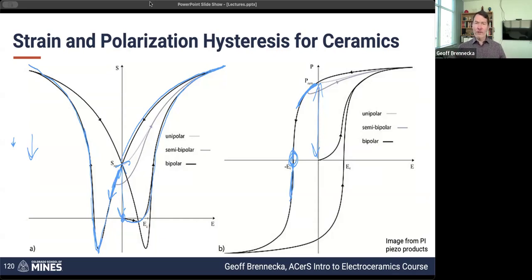So that sounds weird, right? I've started here at the remnant polarization. I don't have any field on the material at all, but I do know that it's poled. Let's say that it's poled up, and I'm applying a field opposite that. It shrinks. And now I keep increasing the amount of field that I apply, and suddenly the material stops shrinking and starts growing again. And that is my indication that I have flipped the polarization, because I've gone through this coercive field.